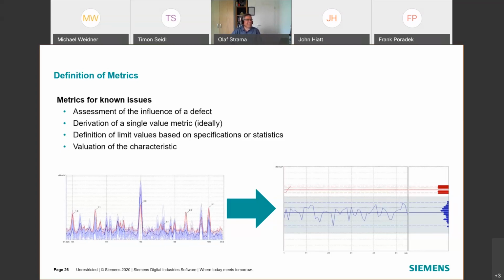Michael Weidner could tell us about cases where an NDT system, for example, has been installed beside a washing machine that uses ultrasonic vibrations. Nobody was aware of this, but we could clearly see the ultrasonic contribution in our spectrum. And this is, of course, something that we need to know, and then we can cut it out in the spectrum and not care about it.